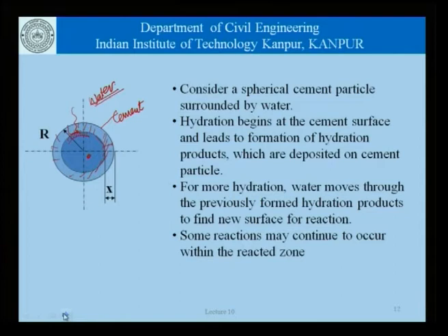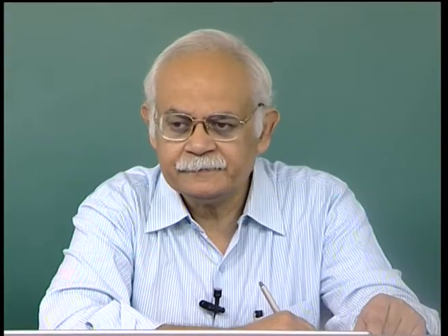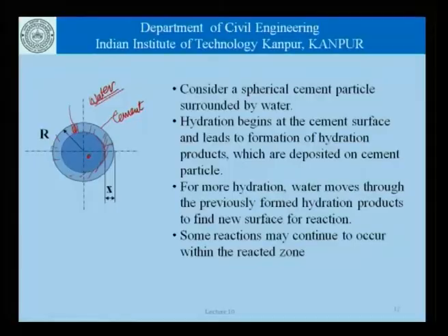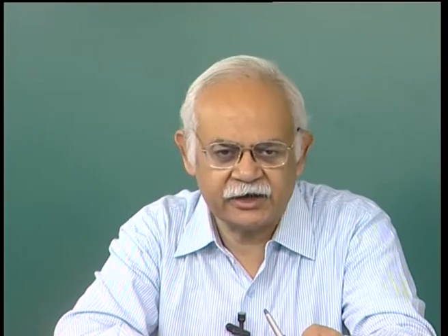Of course, the model can also include the idea that some reactions continue to occur within the reacted zone. So, as the water moves through this layer of hydration products, it is possible that some of the water is also used up in supplementary or secondary reactions within the hydration products, and only part of it reaches the fresh surface of cement and continues the hydration there.